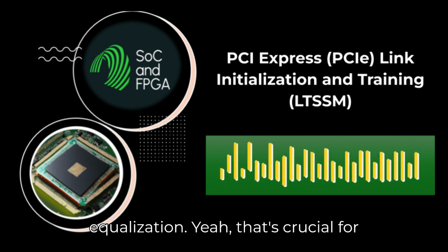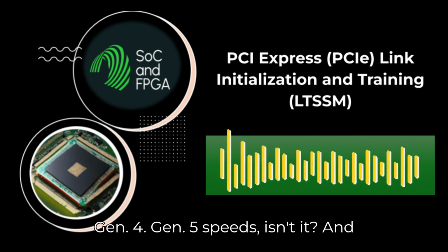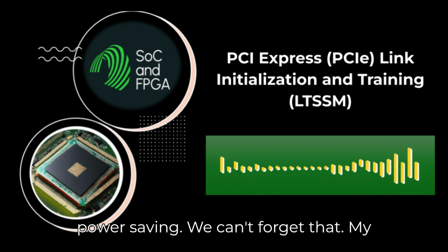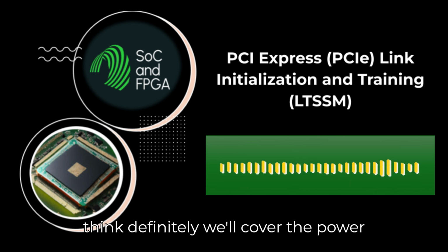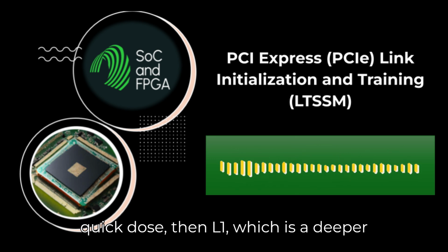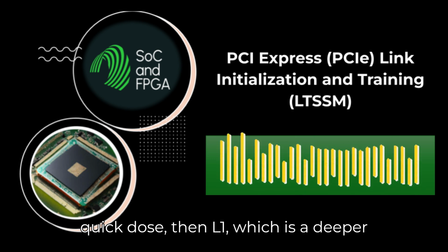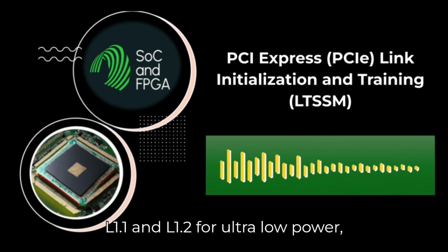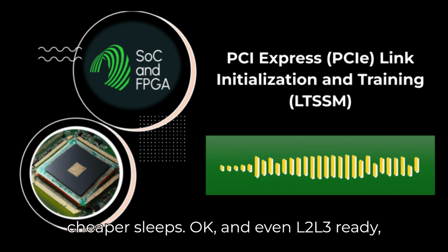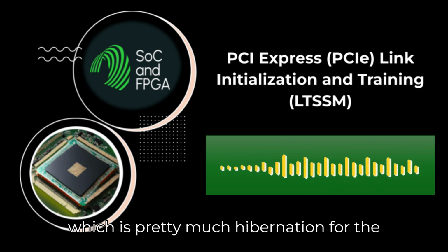Equalization. Yeah, that's crucial for Gen 4 and 5 speeds, isn't it? And power saving. We can't forget that. My laptop battery thanks PCIe for that, I think. Definitely. We'll cover the power states. There's L0s, that's like a quick doze. Then L1, which is a deeper sleep. And it even has substates like L1.1 and L1.2 for ultra-low power. Okay. And even L2, L3 ready, which is pretty much hibernation for the link.